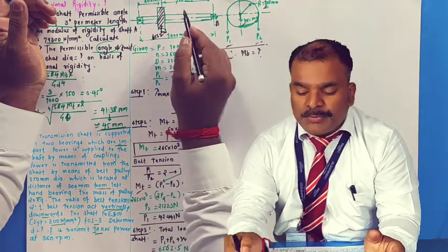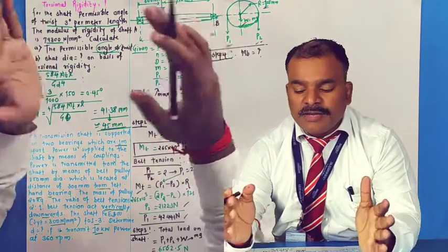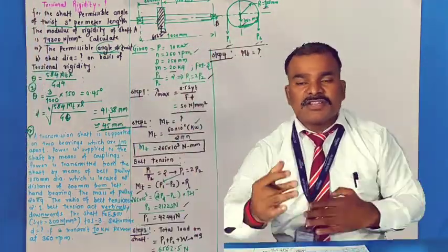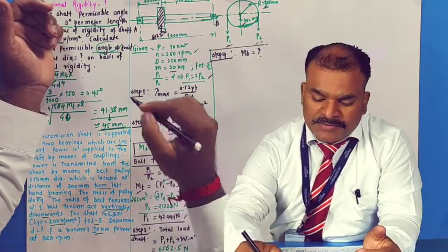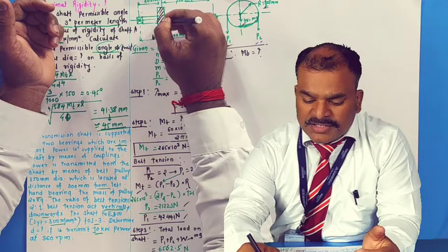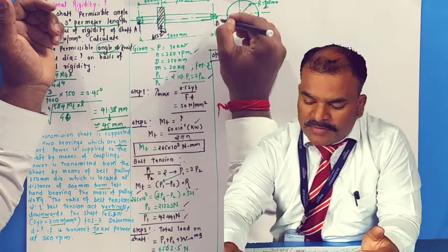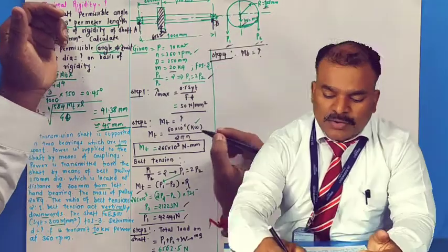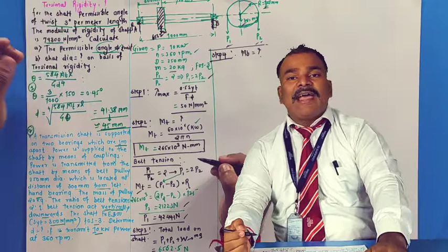But before that, we have attached bearing A and bearing B, both ends, which will take a load that we call a reaction force, a balance force they are doing. Now see, this is the belt acting on the pulley downward. So of course the reaction force is upward, which helps to balance. So I can say reaction at A, reaction at B, RA and RB.